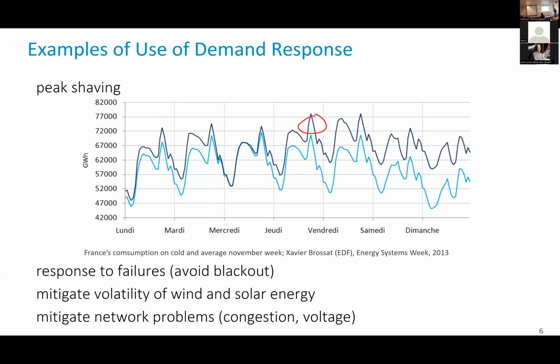That might cause ampacity limits to be violated on some lines. That might cause those lines to automatically trip. So there are circuit breakers that may come into action that could cause another line to break, which might make the problem worse. If a line breaks somewhere, perhaps there's less power coming somewhere, which causes another line to carry more power, etc. It's called a cascading failure. When that happens, an entire grid may be disconnected.